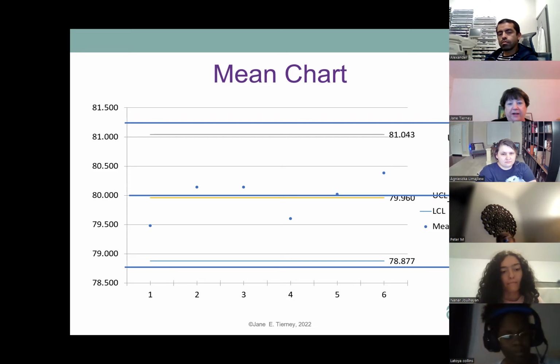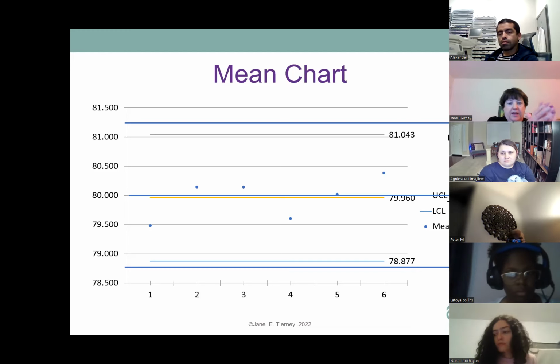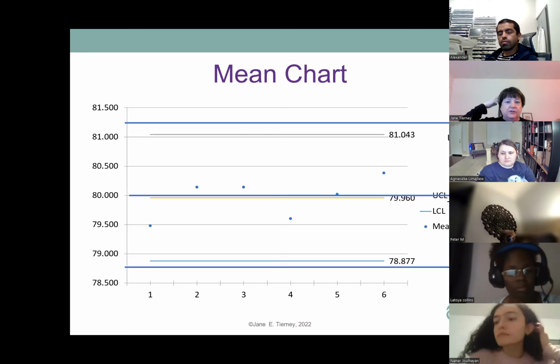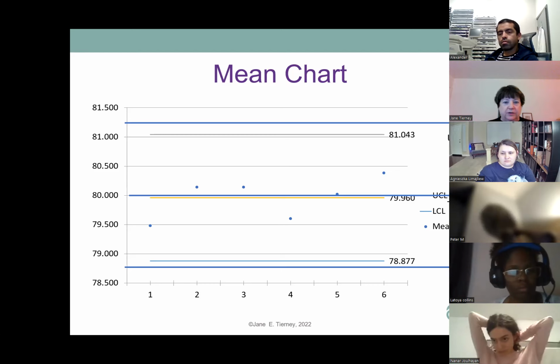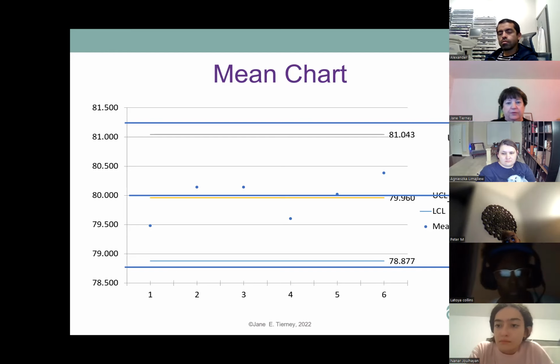So we're going to make 5 batches of 200 parts, and we're going to check some parts in each of that batch. Within that 200 parts, we're going to randomly identify parts to be actually measured and checked. Now, there's a statistical process that tells you how good you want to do this and what samples you should take. And then it gives you an allowance for if you have a reject.